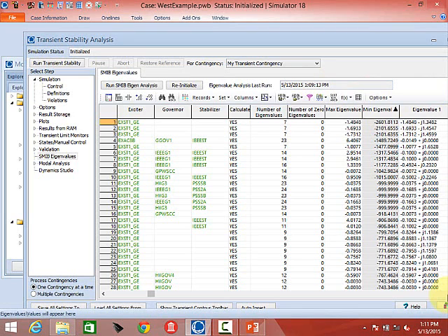That's a mode that decays really quickly. And those modes tend to be associated with these EXST1 exciters, which have very fast response. Unless we did the sub-interval integration, we couldn't handle it. But because we do that, we can handle it. So you get a very fast responding exciter.